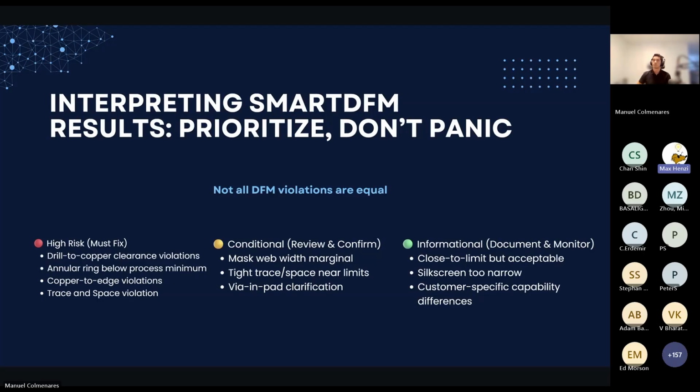As an example, the 6 mil annular ring problem, that design was done in Altium. Altium is, I would consider it one of the most high-end software programs out there. It still occasionally makes mistakes. I sometimes see things in polygon pours, for example, where it will be pouring polygons around pads and traces, say I'm pouring a ground plane on an external layer, and it won't pour between areas where it actually should pour.